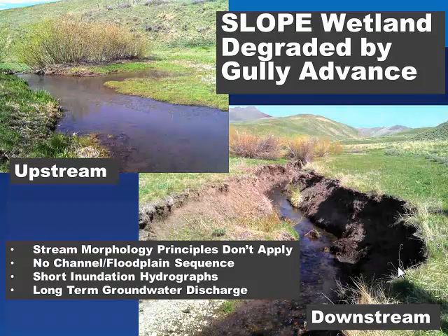As the gully deepens and the channel incises, the groundwater table goes with it, and that surface saturation is lost. Out here the gully is now 6 feet or more below the surface. And we can see some remnant willows there, but they don't have much chance of regenerating because the site of this reach has been completely converted to upland.